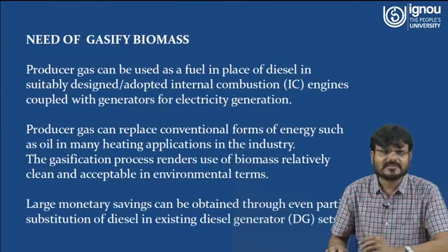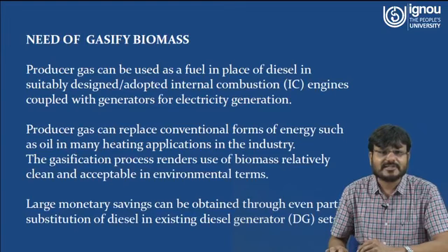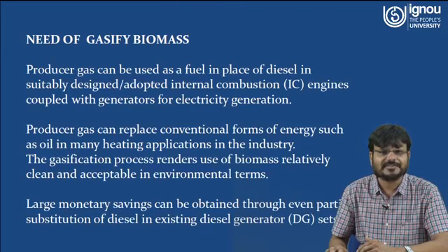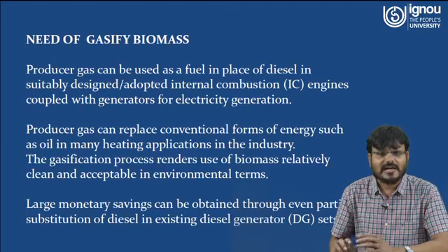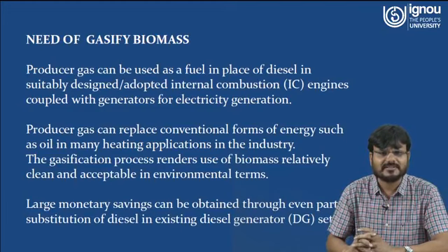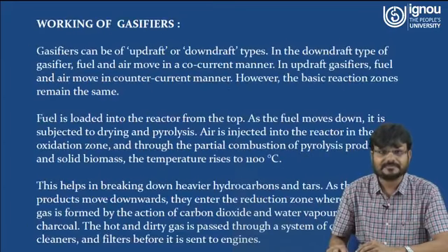Now, the need for gasifying biomass. Producer gas can be used as a fuel in place of diesel in a suitably designed or adapted internal combustion engine coupled with a generator for electricity generation. Producer gas can replace conventional forms of energy such as oil in many heating applications in industry. The gasification process renders the use of biomass relatively clean and acceptable in environmental terms. Large monetary savings can be obtained through even partial substitution of diesel in an existing diesel generator set.